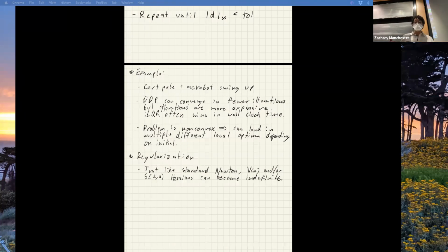So we want to keep things going downhill in the descent direction, we've got to regularize, right? So other comments we saw, it's definitely necessary with the full DDP. And in fact, how exactly you regularize can have a huge performance impact, and means that actually winning with DDP really means you've got to dial that in pretty well.